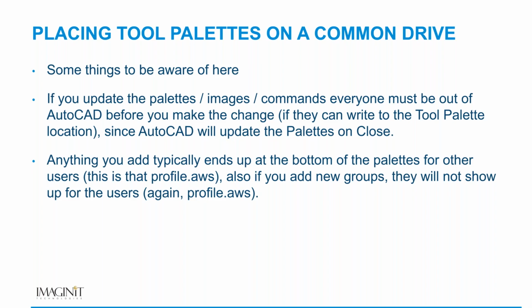In other situations, depending on commonality of blocks, things like that, I might just keep a block, or I might point a block palette back to a directory. And you will see slow performance with everything in one, depending on how many blocks you put in that one drawing. If you're going to do it that way, I try to limit it to 10 or 15 blocks per drawing and see if that helps with your performance.